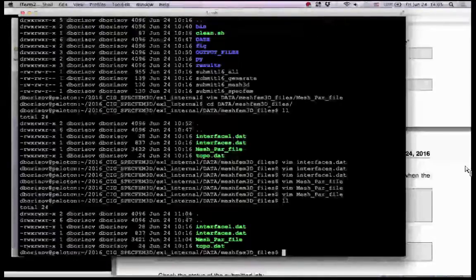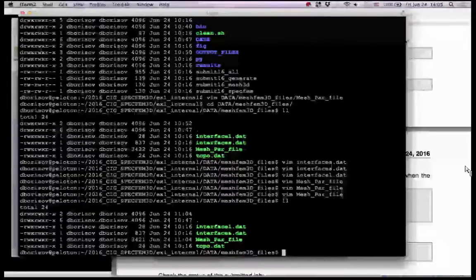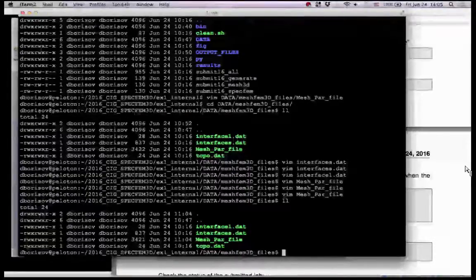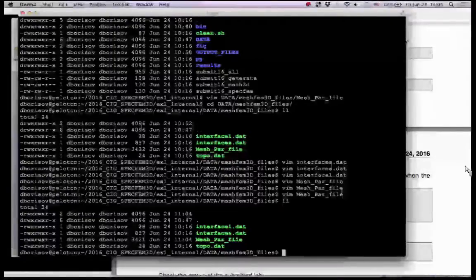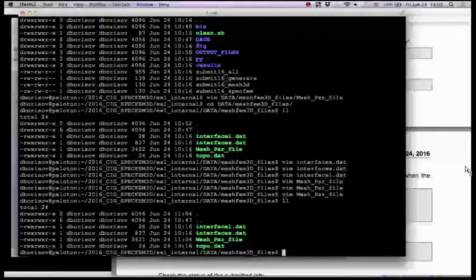Sorry, say again, please. Oh, so right, that's the way you want to build the dimensions of the elements more or less equal in each direction. You don't want to squeeze elements, or it's not good. So you define the number of elements in each direction first, given the frequency range you want to resolve, and then you'll have an idea of how many processors based on the system. Let's say you have 32 cores on the node, so you plan accordingly. There was another question? No?